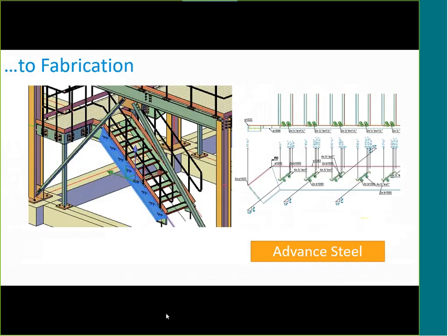But when we do get to fabrication, you do want Advanced Steel. It has tools that make the model so much easier to develop to the full LOD 400 that's needed for the construction fabrication time. For example, as I mentioned before, creating steel railings and stairs to this full level of detail should not even be attempted in Revit. The documentation tools are very helpful, designed specifically for fabrication, where the Revit documentation tools are useful but generic.